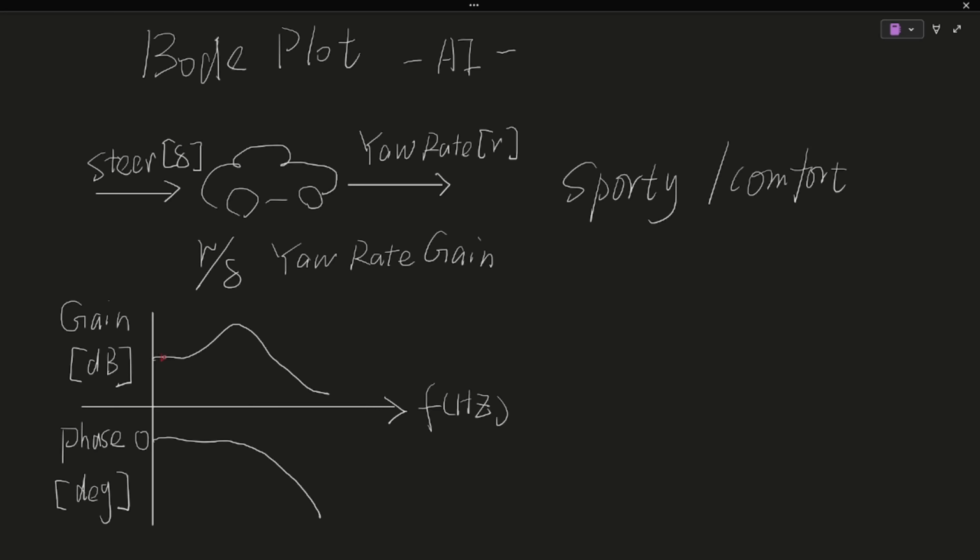In the low frequency here, in this range, the low frequency means the steering wheel is turned very slowly. In this range, the yaw rate gain remains constant, which means this is steady state.